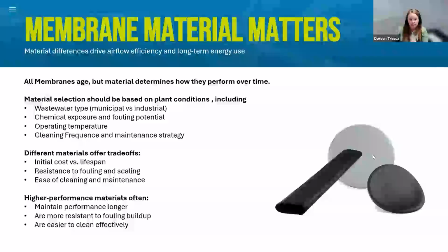You also have to think about maintenance strategies. Some municipal plants don't have an operator on site all the time. Do they need something that's going to last a little longer between cleanings? Is it going to be easier for them to clean and maintain? So when you're either an operator for a plant or a salesperson looking to spec out a plant, you have to understand the differences and see it from the operator's level. That's going to help you make the right decision for your membrane.